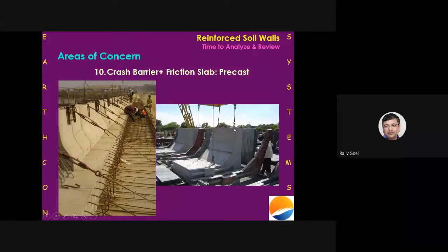I did tell you that in case you are doing a full precast unit, it is still possible, in case you are able to manage connections with the adjacent units. So this is one such construction where you have the shear keys designed to engage the adjacent units when one unit is taking the vehicular impact. So you have male shear keys on one side, and you have the female shear keys on the other side. If you do that, it is equally good as an in-situ connection.